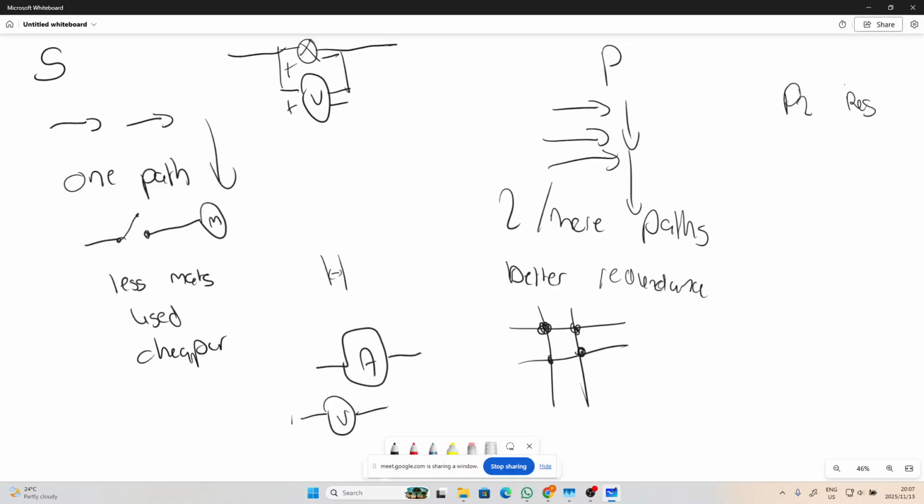No matter how many bulbs you connect, let me simplify all of these practicals. Connect more bulbs in series, they get dimmer and dimmer until you can't provide enough current. Connected in parallel, they will all look the same and shine at maximum brightness but use the most current. Simple stuff.